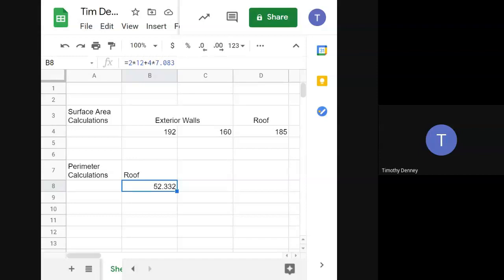At Lowe's or Home Depot, you'll see some that are 10 feet, you'll see some that are 10.5, okay? Sometimes you'll see smaller ones, but I saw a lot of 10s and 10.5s. I'm guessing the reason some are 10.5 feet is because when you put drip edge on, you're supposed to overlap a little bit, right? So essentially, when you purchase two pieces, you're going to overlap them probably about half an inch. So you're really only going to be able to use 10 of those 10.5 feet as far as the total distance. That's probably why they're 10.5 feet, to account for that overlap.